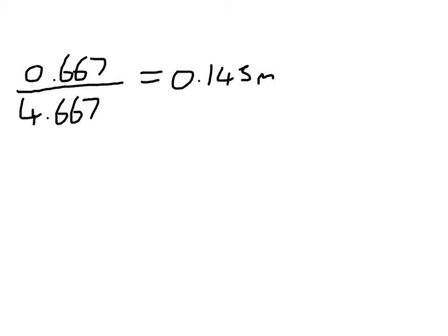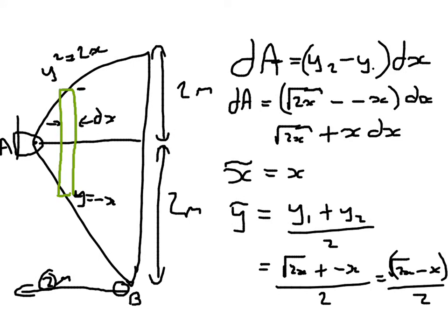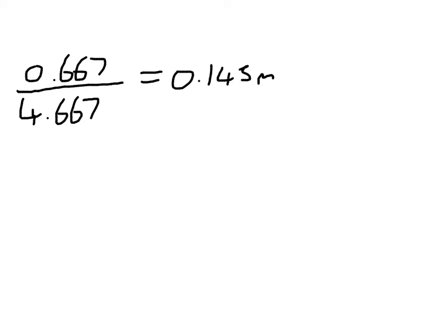So all the way back in our original question, we now know where our force sits. So we now know we have a weight acting here, and we know our x direction is 1.26 metres, and we know our y direction, which I haven't drawn very big, but is 0.143 metres upwards. So now what we need to do is calculate our support reactions. Well, first of all, we need to calculate a weight. So our weight